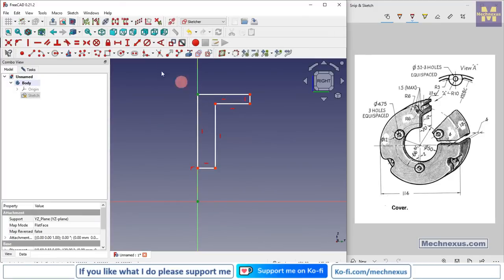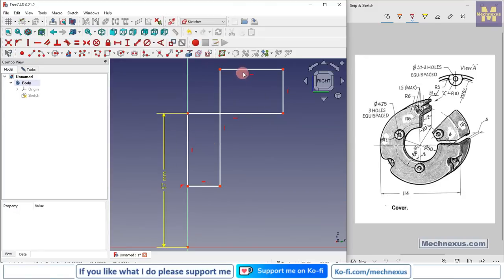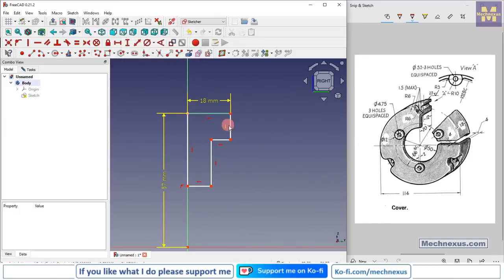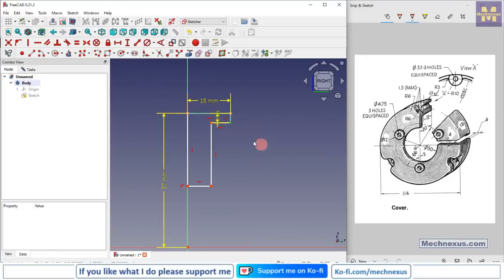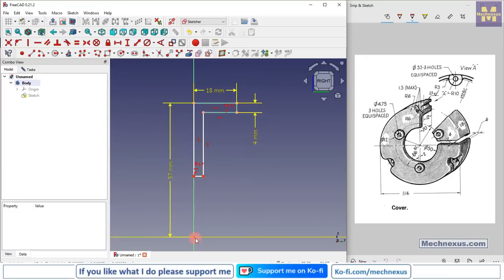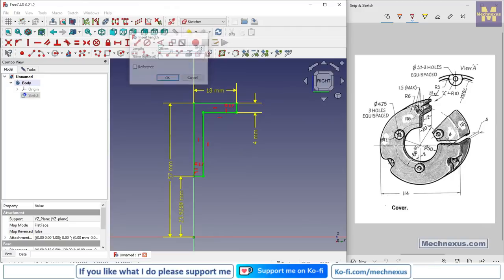So select this point and add a horizontal dimension of 57, and move it and add this dimension 18 mm, and this is the 4 mm, and select this line and press Ctrl key and select both the lines and add an equal constraint, and from this point to this point is 25.